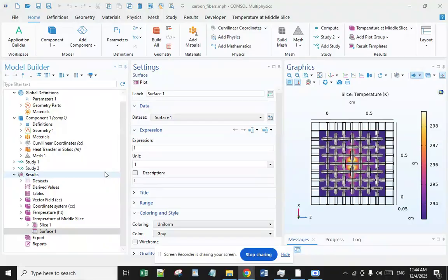The contact resistance may be reduced by immersion in glycerol, but this would not be recommended for dry fabrics, as the glycerol would infiltrate and loosen the fabric structure. In fact, as glycerol is still used for the rest of the contact surfaces, researchers sealed the dry fabric samples to avoid glycerol infiltration.